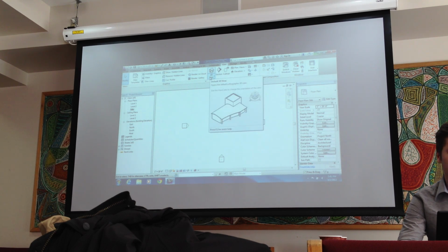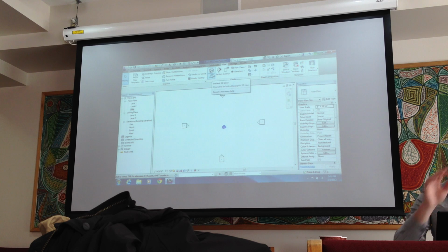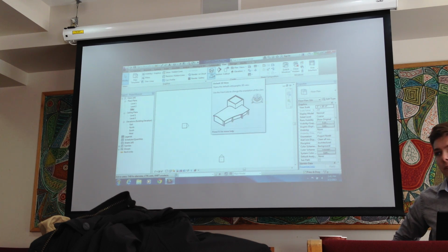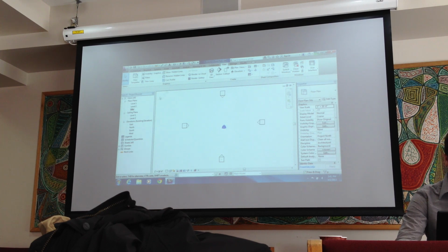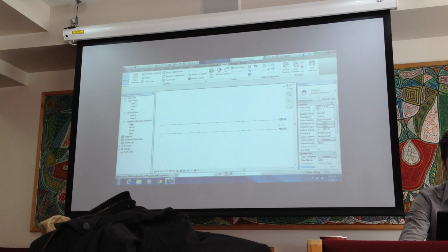Okay, what you can do for this instead, I'll show you how to add floors, and we'll create that first, and we'll go to topography. So you have basic level 1 and level 2 and items like that, correct? We have level 1. Okay. So we'll start by creating different levels and sites instead. So if we go to level 1, or sorry, let's go to elevation first.